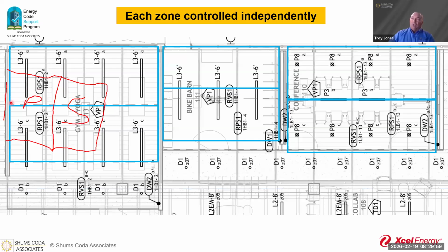across here from this original primary zone, and this light here was only 150 watts, we could actually do that control there. This one here would still have to be under control of this primary zone for this window. Same with our secondary. If we were able to do that, we would be good. Obviously, over here, these two would be under the control of this one. Or if for some reason this was less than 150 watts, you could do the control here.